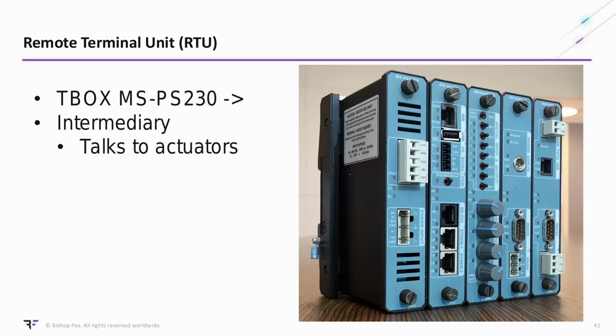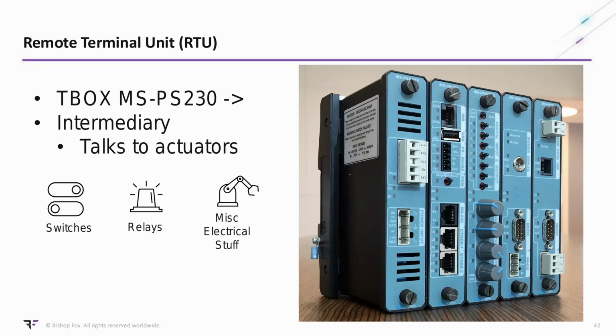The main purpose of the RTU is to serve as an intermediary between those shot callers, the energy management system folks, and the actual devices that actuate the electrical network. So switches, relays, and just miscellaneous electrical stuff that need to physically move a wire over here so that it disconnects this network and reconnects that one, or changes this voltage to that one, or if a telephone pole is dangling in a road, that we can disconnect it, right? That can happen in a split second rather than hours as somebody drives over to it. So that's the purpose of these things.